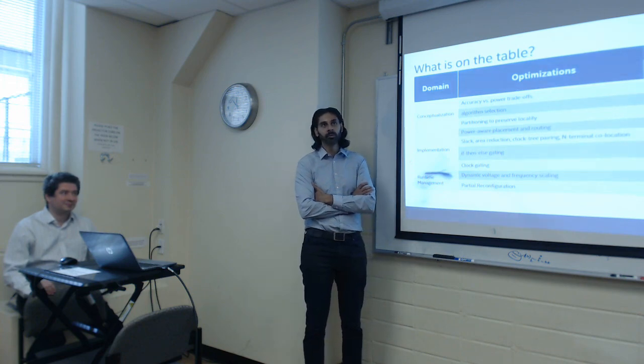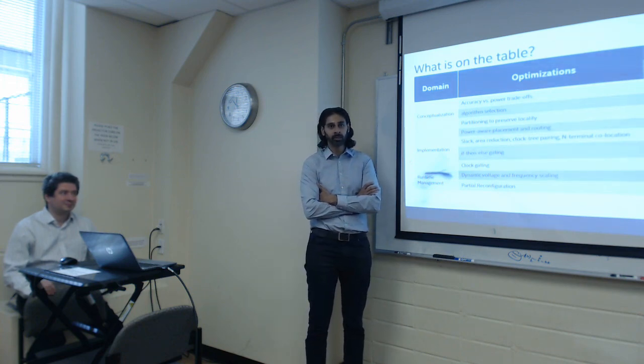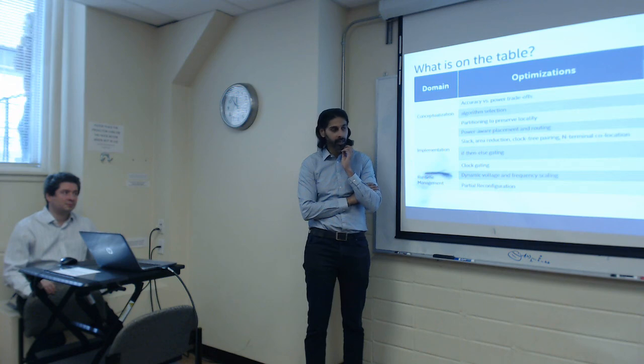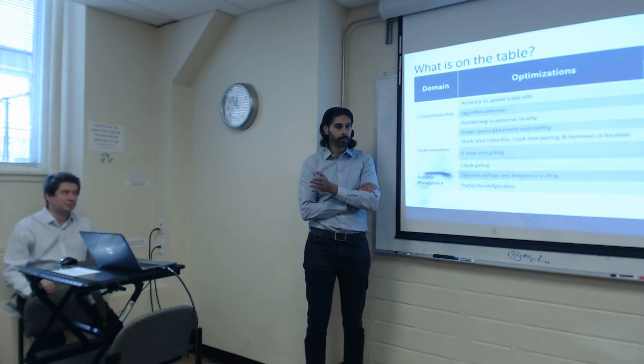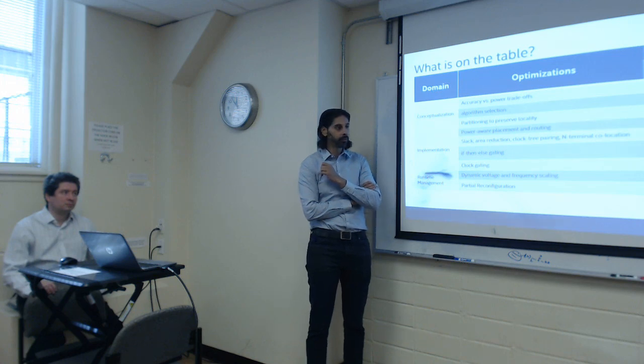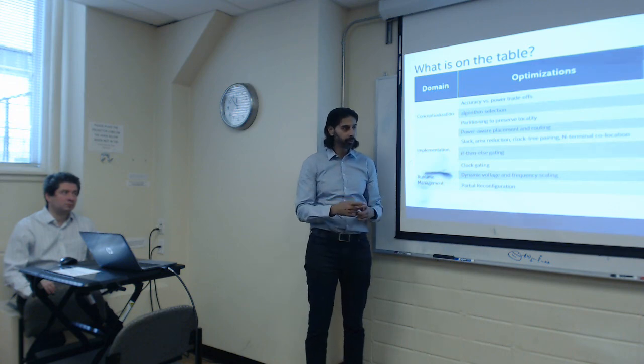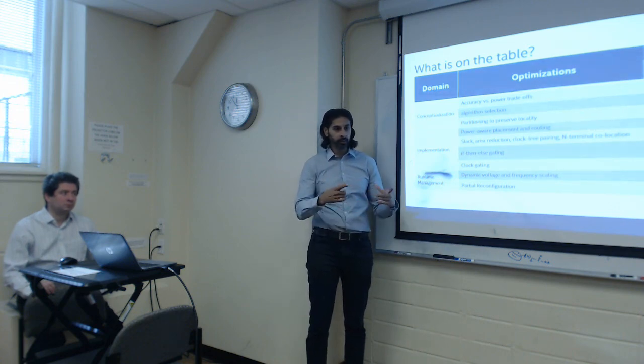So I won't be able to divulge the actual numbers, but EPE is not yet public, as Vaughn mentioned. You're right, we used to have body bias in Arria 10 and previous families. We don't have it in Stratix 10. I think this is public information. But what replaces that is the thing I just mentioned, Smart VID, where you're no longer controlling the static power within local regions of the FPGA. You're controlling it at the chip level.